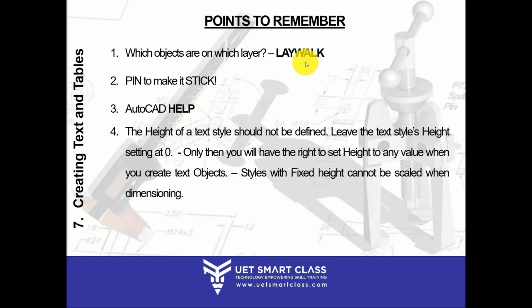Because when we have a quite complex drawing which we are working on, it becomes really hard to check which objects are on which layer. So this is a very important tool which we can use, because through this we can check the layers. This is called LAYWALK. If you use this, it will help you to know which object is in which layer.